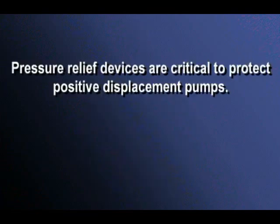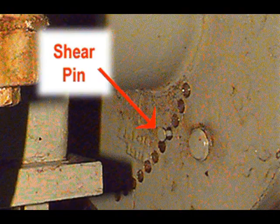Pressure relief devices are extremely important on any positive displacement pump. These devices can save considerable cost and damage to pump system equipment because of blocked flows and high pressure buildups. If excessive pressure buildup occurs, the eccentric flange shear pin will fail, or a discharge pressure switch will open to shut off the driver. While the shear pin and the driver shutoff device should provide adequate protection, if they do not, the pressure relief device becomes important.